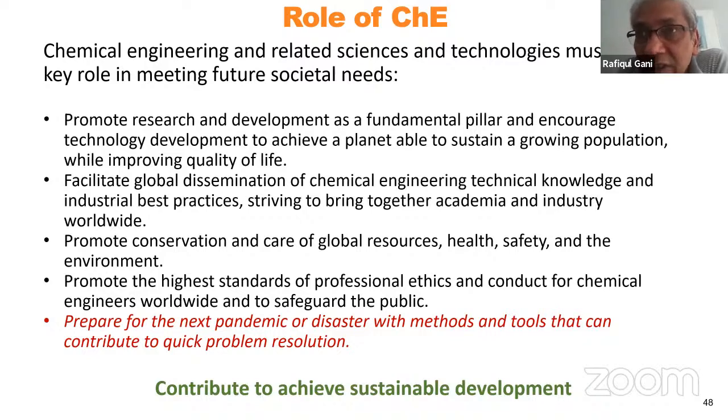And also, what has been shown in recent research is that it is not even a problem from a control point of view, from an operational point of view. The reactive distillation or dividing wall column with non-reactive reaction can operate and can be controlled very well. So there are no difficulties in operating. It's just the initial incentive of the companies to invest in this solution and see what can be achieved. That initial breakthrough is difficult to achieve. But from my private connection with some of the companies, they have developed pilot plants, and I would guess that the next step would be that they will expand from the pilot plant. So it depends on the company whether they're interested to do it or not. But the potential is there.